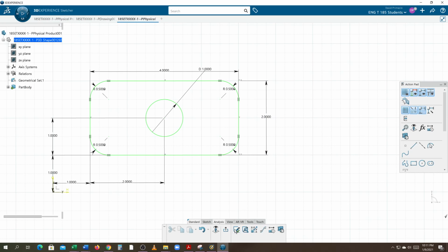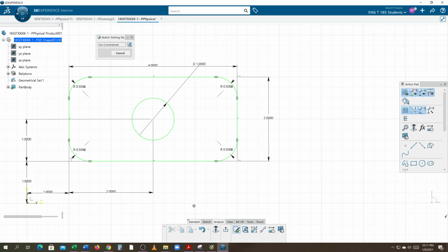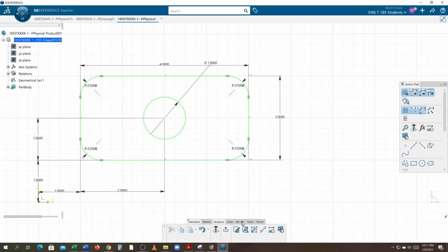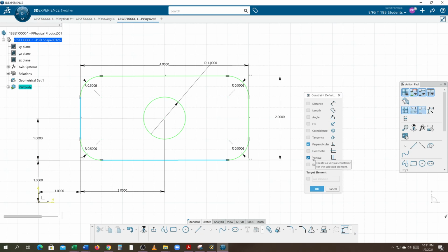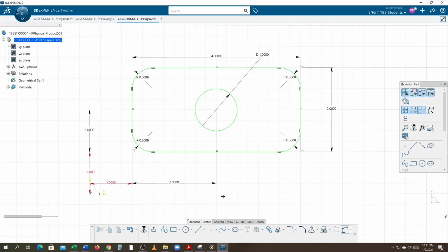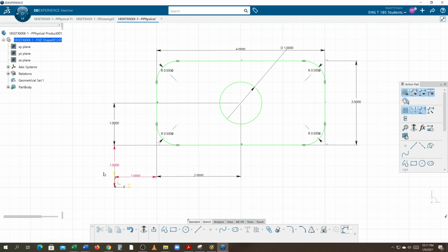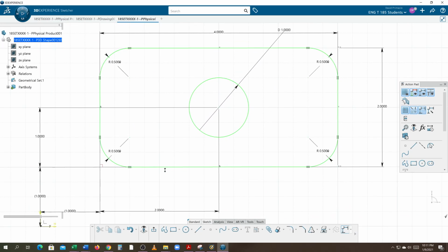I'll close this off, click on this, and it says it's constrained. The only thing is I'm missing my datums. When I come over to this line and use my control button and grab this line so I can do both at once, we can go into the sketch dialog box, which is the second one here on this list, and then pick horizontal or vertical to turn them off and fix to turn those on. Select OK. I've established my datums, but these 1-inch dimensions became red because once I established the datums, these are not needed. But I like to keep them on there as reference to know that I'm truly at 1 inch off that coordinate. So the intersection of where these two lines are will be 1 inch off that coordinate. And just like that, this part is done.